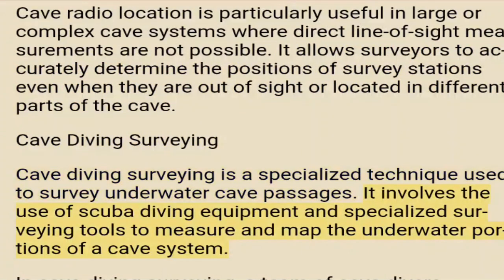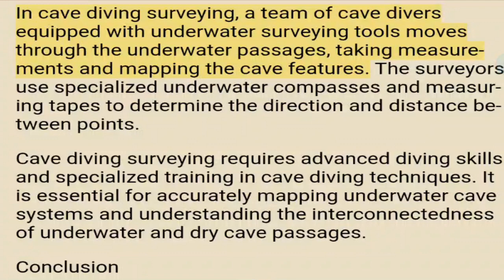It involves the use of scuba diving equipment and specialized surveying tools to measure and map the underwater portions of a cave system. In cave diving surveying, a team of cave divers equipped with underwater surveying tools moves through the underwater passages, taking measurements and mapping the cave features. The surveyors use specialized underwater compasses and measuring tapes to determine the direction and distance between points.